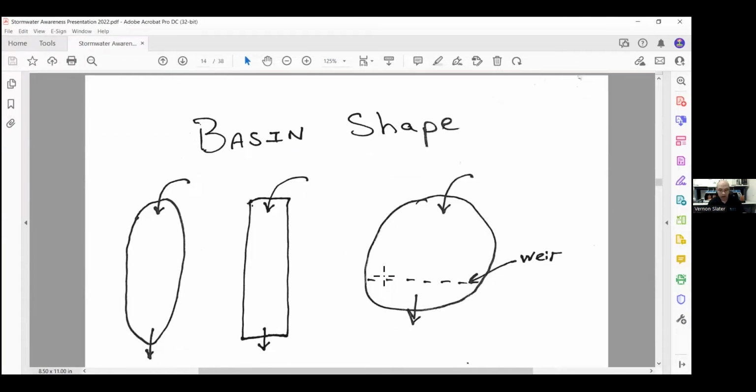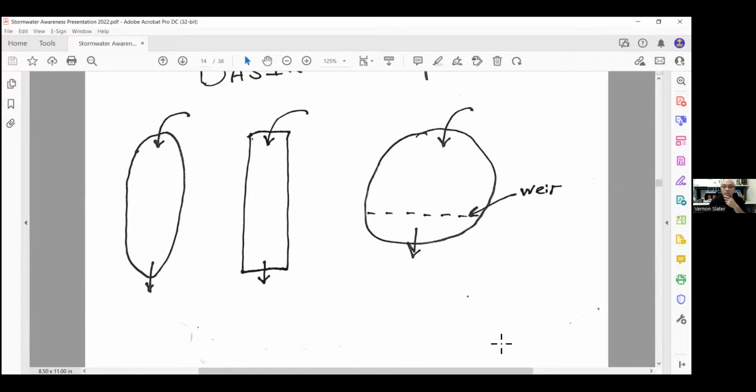You're going to need 90 minutes of contact time as a design feature that will need to be met. And with designing a basin, perfectly round basins are not the best design for footprint use. Short-circuiting the pond can occur. Therefore, oblong, rectangular, and divided ponds are highly recommended. So we've got our oblong, our rectangular basin, our round basin with a weir wall.